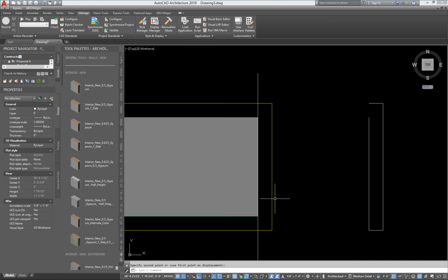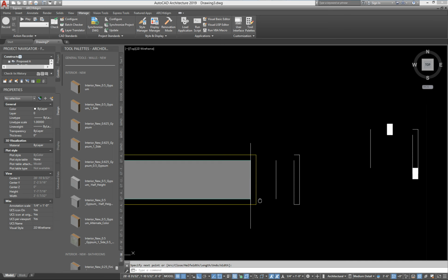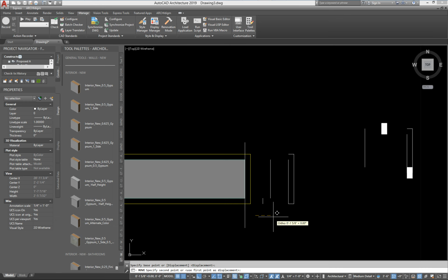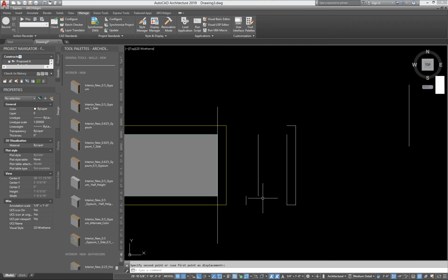The next thing I want to do is draw a polyline that tells the stud wall what to do. And I can draw it just like that. Now I'm making the length match. Again, when it's a straight edge like this, you can make it any length, it doesn't care. I could have drawn it 1 inch and it would still work. And then for the final part, I'm going to draw this little piece here, like that. And I'm going to move that over. And once again, any length. In fact, you only need 1 of these. You just click on it twice for the straight segment. But I like to draw them all out because, especially when you get more complicated walls, you really need to visualize the whole thing and keep them all in order.